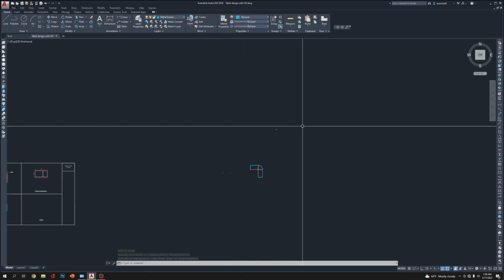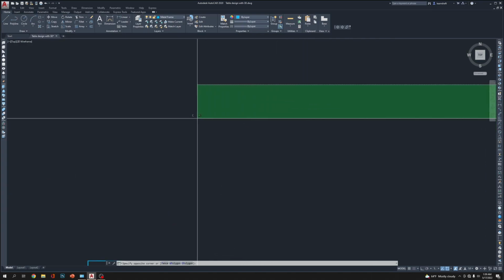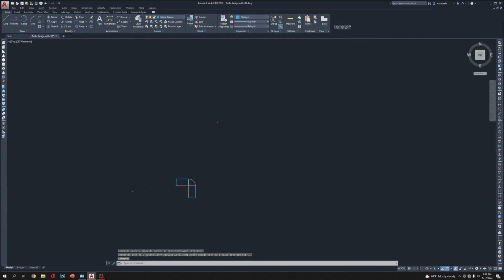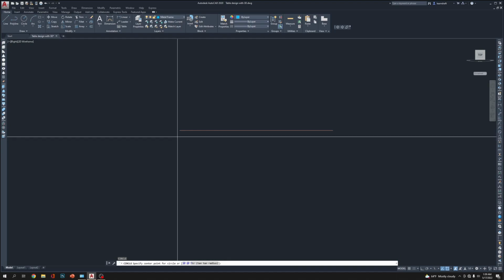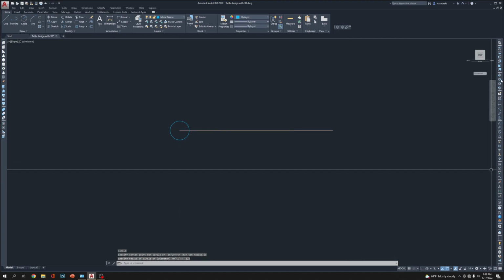So this is we are in the top. If you go to the side view, we need to see it from this side. So we're gonna go to the right view. Here's the right view. Circle. We're gonna draw a circle here, 0.125, enter. Go to the isometric view.